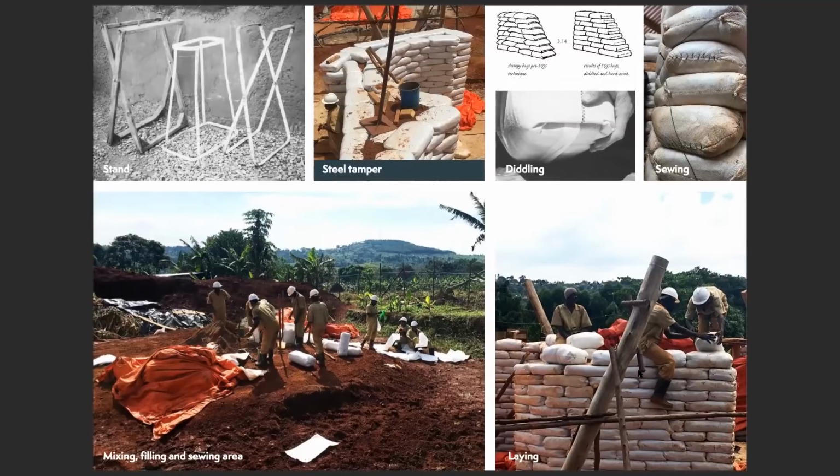We are looking to achieve a certain strength, about 1 megapascal in this soil, and the soil that we have from the site was not giving us that. So blending with sand was allowing us to compact it well to achieve that strength.